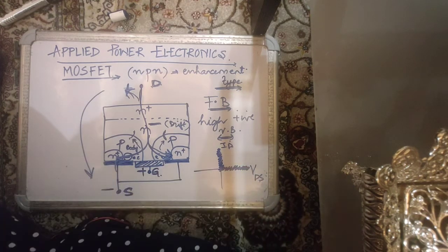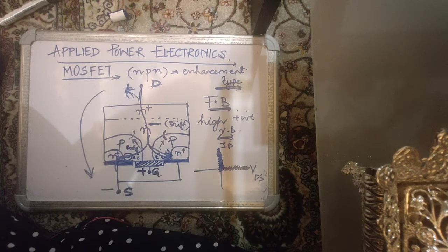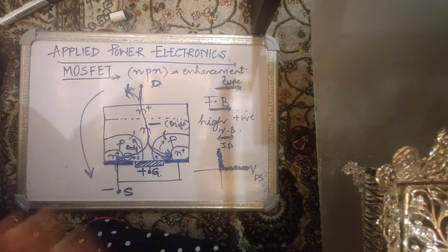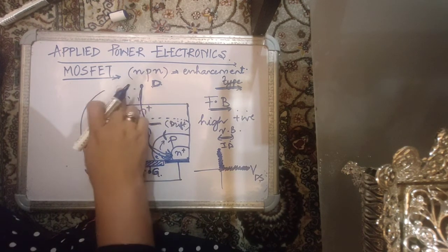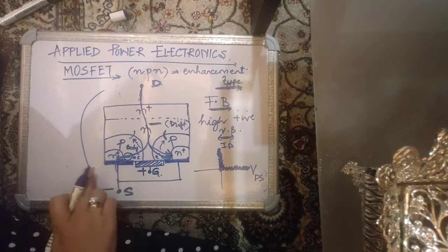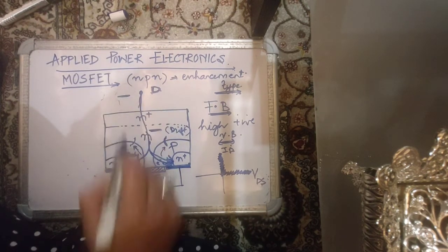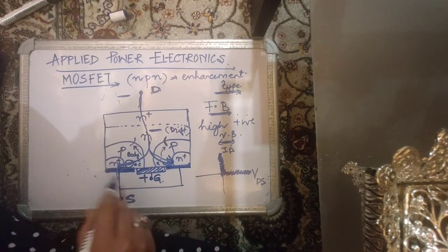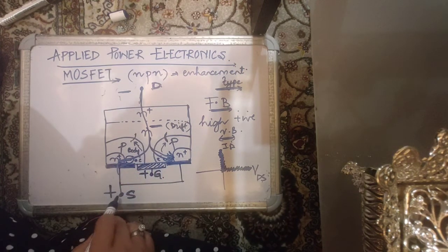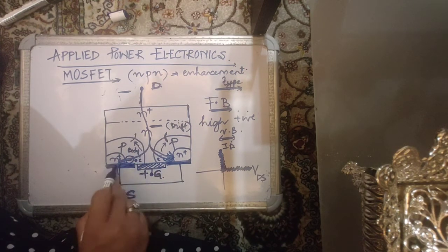If you remember our previous lecture, the first lecture for that matter, you would know that the MOSFET can also carry negative currents. Let's see what happens when we give a negative voltage to this power MOSFET. So if I make the drain negative and the source positive, let me go back. If you see this, the source is body shorted, which means that the p-type body and the n-type source are shorted.